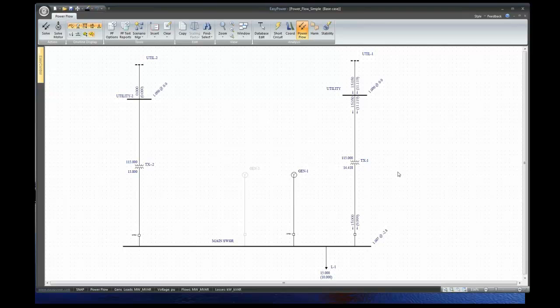If you have a utility system with step-type voltage regulators, which are basically auto transformers with a load tap changer, you can model those as just a two-winding transformer with an LTC, just a 1-to-1 voltage ratio with an LTC and very low impedance. We don't have an explicit auto transformer model, but you can model it as a two-winding transformer. And then you can put in the LTC and it'll function just like we showed here.